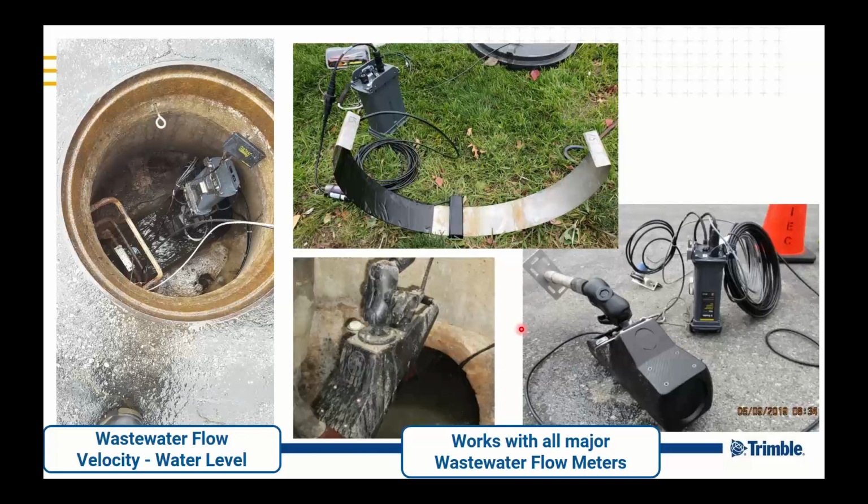So here are a couple of different instances of our equipment, how it can be used and how it can be installed and mounted into the manholes that you have out in your system. So the top center here is our AV sensor tied into a 15-inch band installed as part of a flow monitoring study for alarming and for SSO monitoring. And what you see down here is our Raven-Eye 2 installed in the manhole.